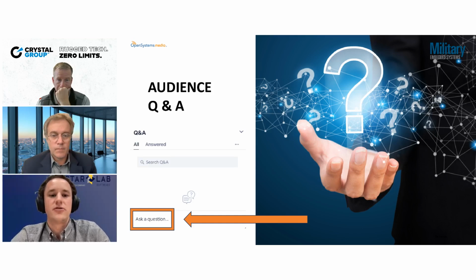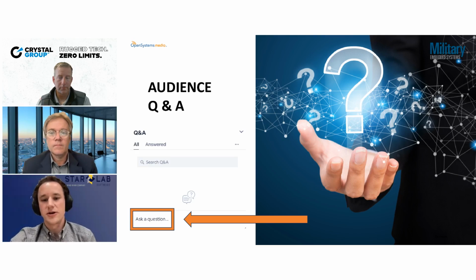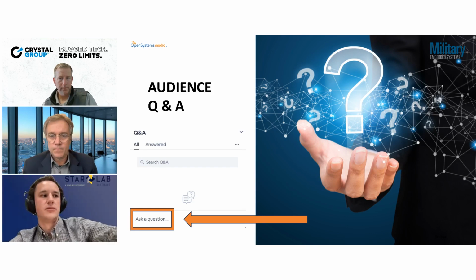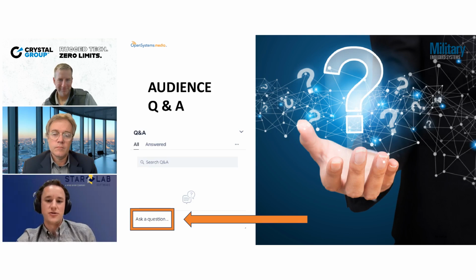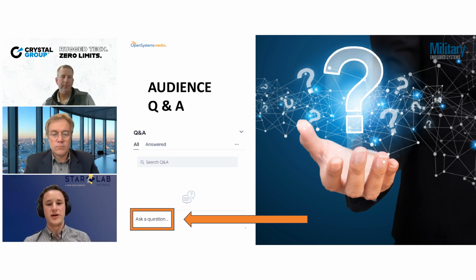So the way we think about it is there's a lot of things you can do with using lighter weight encryption protocols, with using hardware acceleration, AES acceleration for a lot of different things, trying to rely very carefully on validating things early rather than continuously. And honestly, the biggest thing is upfront. When you've designed your system and thought through security, you do your risk assessment then, and you make sure you only add in the security controls and limits that you actually need. For a system that's being deployed somewhere locally or under physical control, you need very different security than something that's being deployed autonomously somewhere else where maybe someone we don't want can lay hands on it. Those are two very different scenarios, and so you need to apply two very different sets of security controls to them.